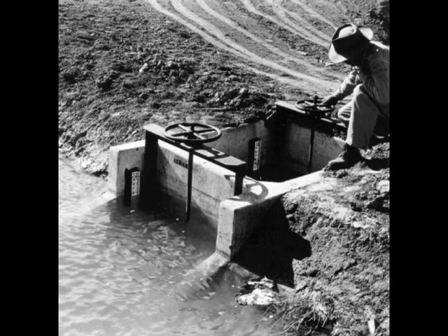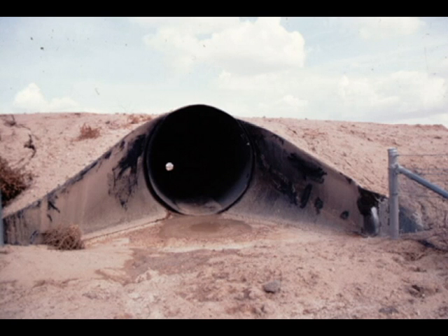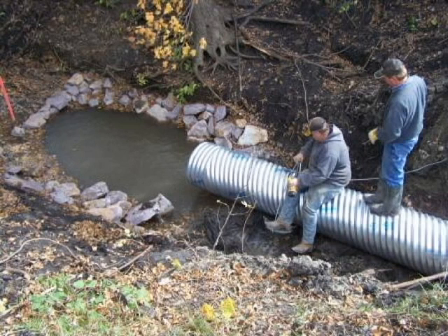Turnouts should be placed so that it is not necessary to check the water above the design flow of the ditch, thereby providing a safety factor if water is turned down the ditch with the check flashboard still in place. Crossings should be provided so that equipment will have access to all parts of the field. With pipe drop structures, a crossing can be provided by extending the length of the barrel and increasing the width of the fill.